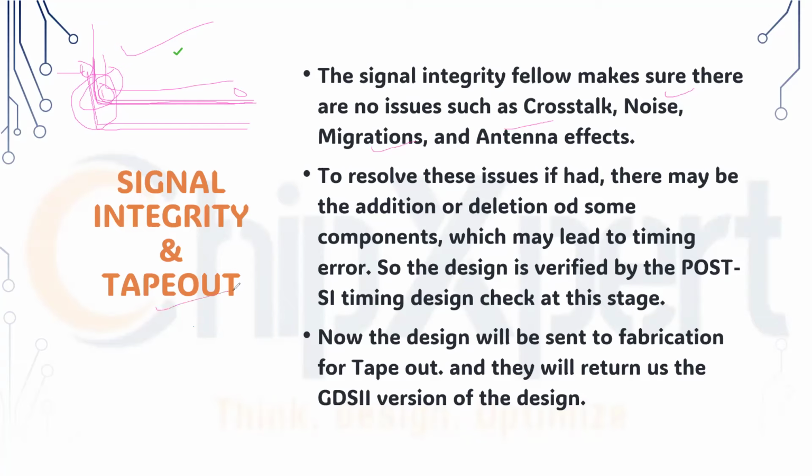Okay. Let us tape out. We are done with all the processes of this chip. We are taking the design, completely tested with the functionality and everything, and we are taping out for fabrication. We are giving our design to the fabrication unit, that is called a tape out. The file is currently in GDS2 format. This is not a human-readable form, so this file is only submitted to the fabrication unit. Okay, so this is all about the VLSI design flow.